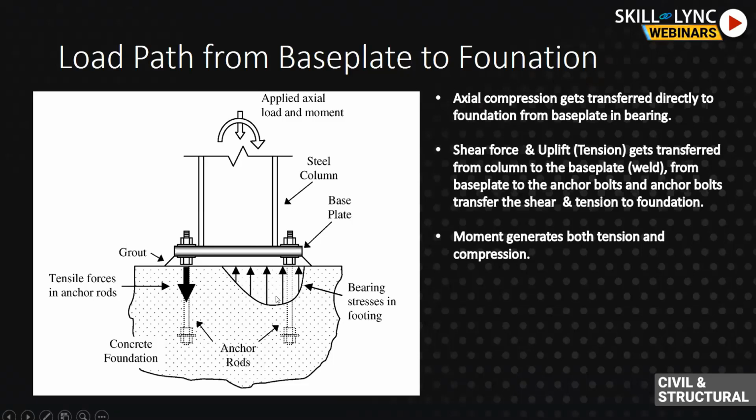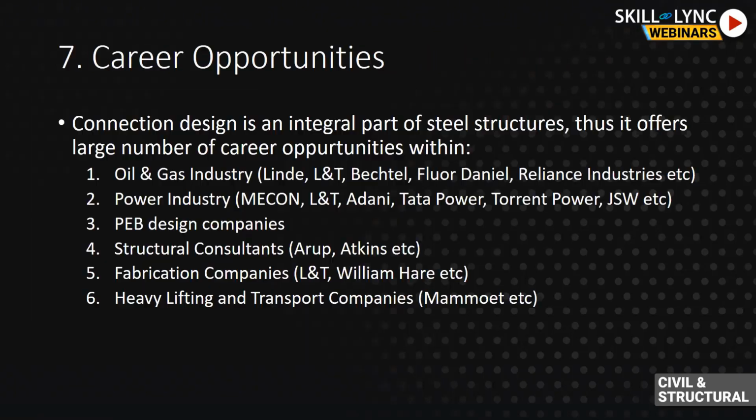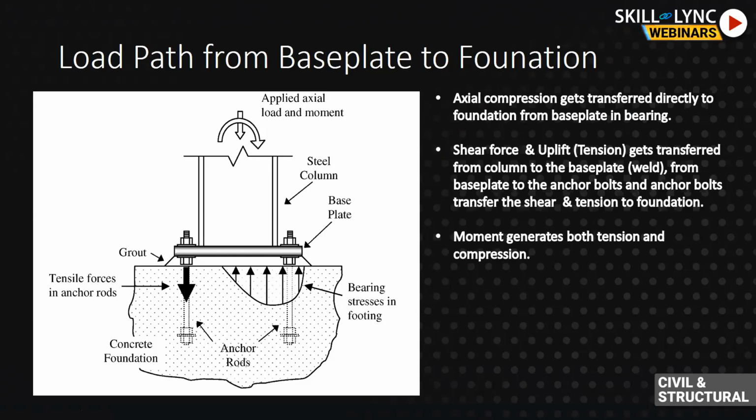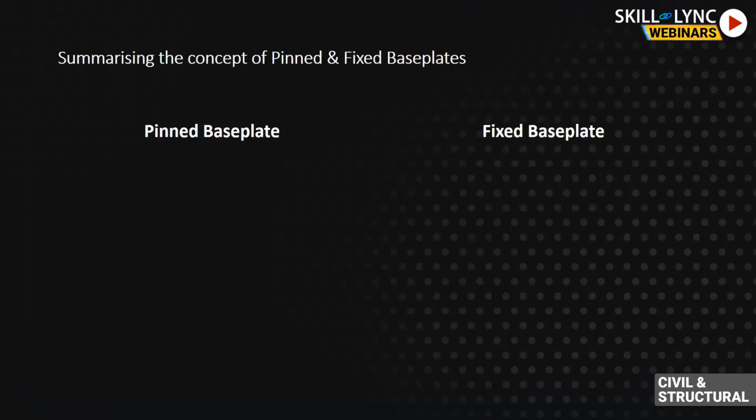So when it comes to moment, the two anchor bolts in a four anchor bolt base plate will come into picture for resisting just the tension forces, while the compression will be resisted by the bearing on the concrete. So now that we are done with the load path, we'll summarize the concept of the pinned and